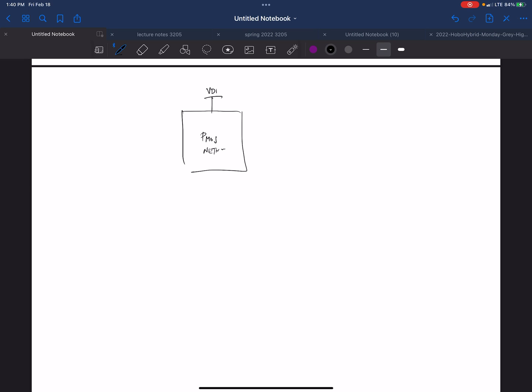So this is your VDD. It's clear to you guys, VDD in this class means your highest supply in the process. In our projects, it's 1 volt. And then ground, you have your NMOS network, and the input goes to both, and the output comes from where they meet.